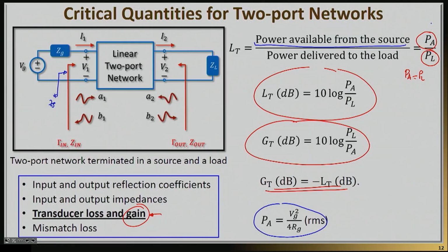Now you might say, why are you comparing the power that goes to my load to the power that is available from the source, and you're not comparing that to the incident power of this network? Perhaps the incident power of this network is not the same as the power available from the source. Well, the answer to that is make it the same. It's really your responsibility as a designer to take as much power from the source as you can.